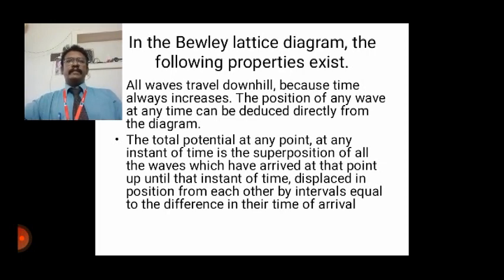In traversing the second line, if we keep the attenuation factor as K, then on reaching the end of the second line its amplitude would be reduced. This happens not only for voltage surges; almost all abnormalities face this kind of issue. The lattice diagram may now be constructed as follows. Set the ends of lines at intervals equal to the time of transit of each line. If a suitable time scale is chosen, then the diagonals of the diagram show the passage of the waves. This is the way the lattice diagram can be constructed by putting a few more parameters in the lattice.